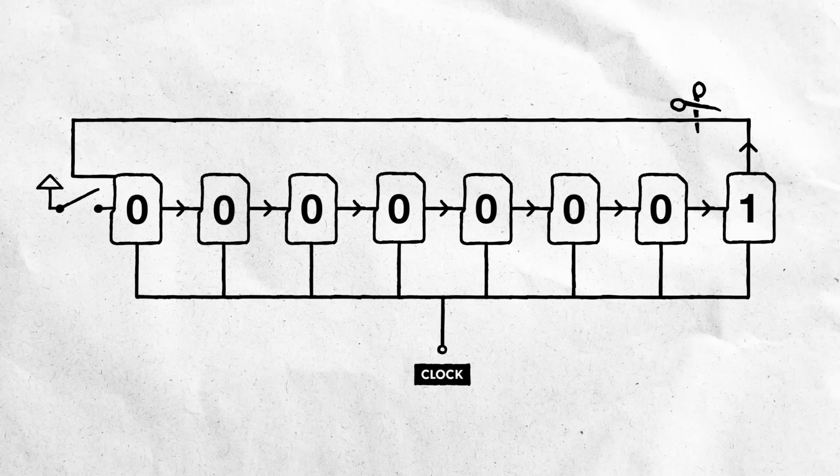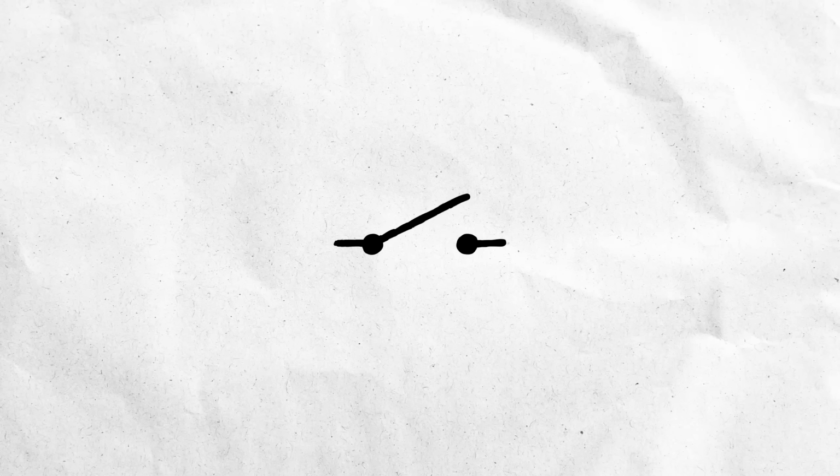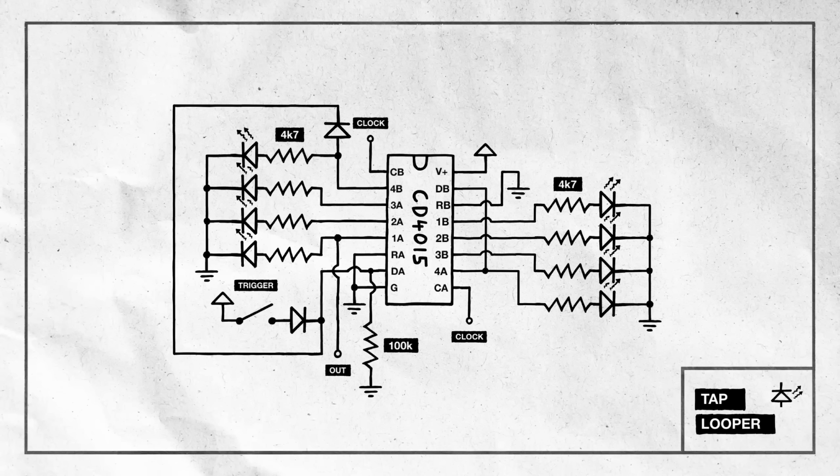Implementing this isn't straightforward though, because most push buttons are normally open. They only connect when pressed. So if we'd put one into the feedback loop, the connection would be broken by default, and the sequence wouldn't loop unless we held the button down the entire time. To work around this, we'll use a PNP transistor. If we place it in the feedback loop like this, it conducts by default, unless its base gets pushed high by the button, in which case it blocks and breaks the loop.